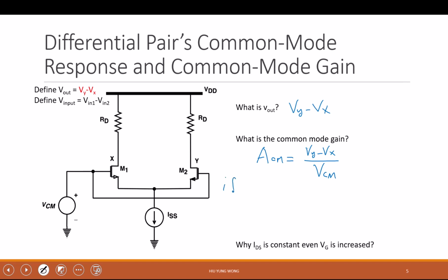If VG1 equals to VG2, right? Because now it is common mode, right? I do change the gate voltage. But is this circuit still symmetric? If I make both VG goes up and down, is it still absolutely symmetric, this circuit? Or on other hand, if you were an electron here or here, do you feel the same electrical potential? Do you feel the same environment? If both of them have the same gate voltage? Yes, right? So they are still symmetric, regardless of what value you have.